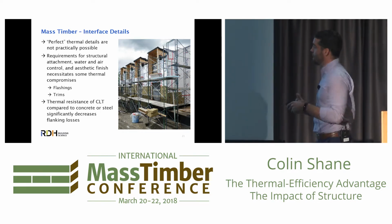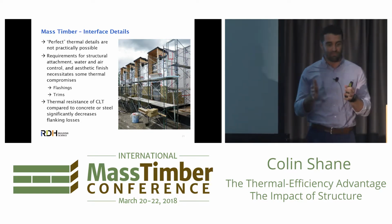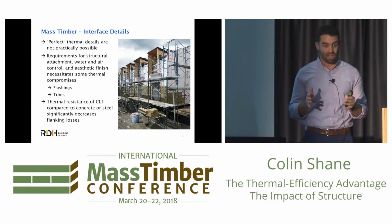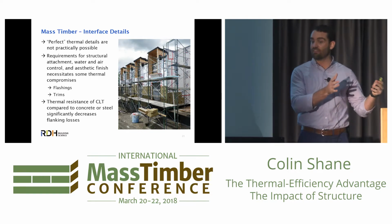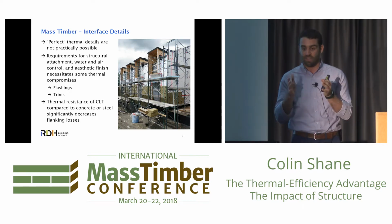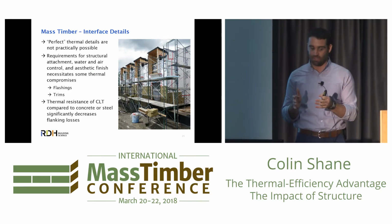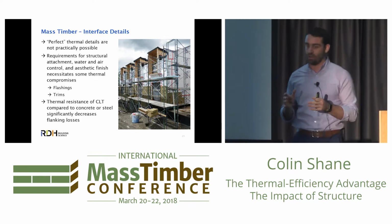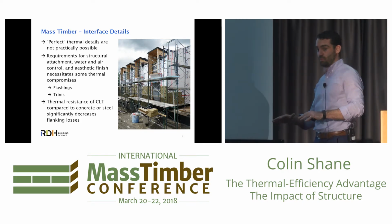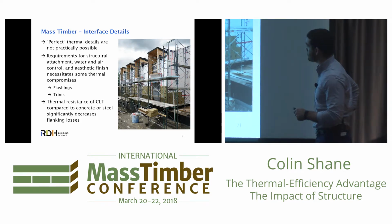between assemblies. The benefit of mass timber here is that because you have decent thermal insulation in your structure itself, even if your linear interface detail isn't perfect and you have some bridging of your insulation at interfaces, the actual thermal resistance of your structure that's going to be continuous through that detail can really benefit you in the long run by lowering the linear transmittance values across those interface details.